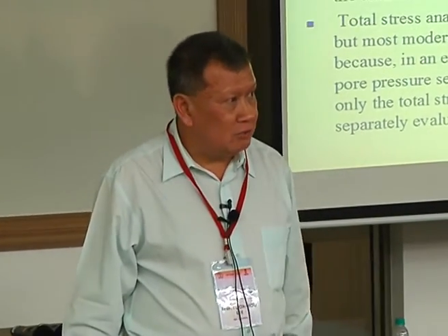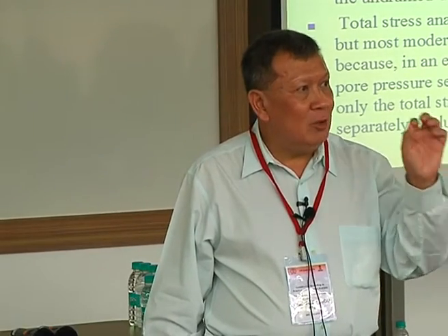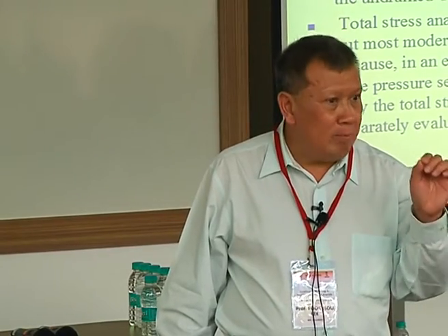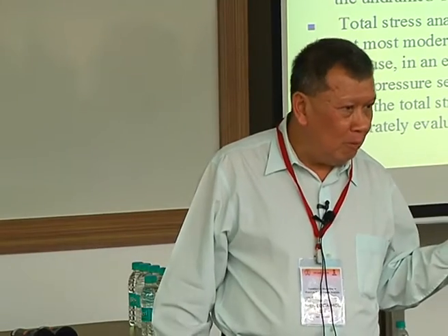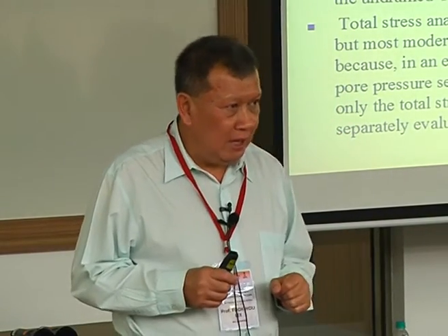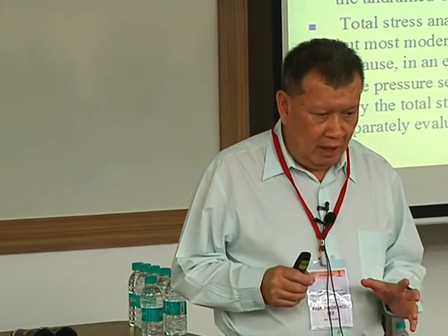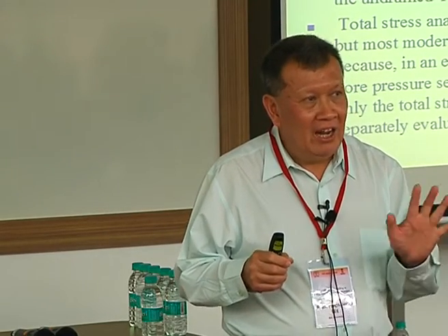If you want to do a total stress analysis, you can always do it because you assign E to EU, you assign nu to 0.49. I think you turn on the non-porous. The moment you turn on the non-porous, it won't compute the pore pressure for you. So you won't see it. And even if you don't turn it on, what you do is this. In programs like GeoFEA, you can do the same thing by assigning E to EU, nu to 0.49. And then you treat it as a drained analysis.